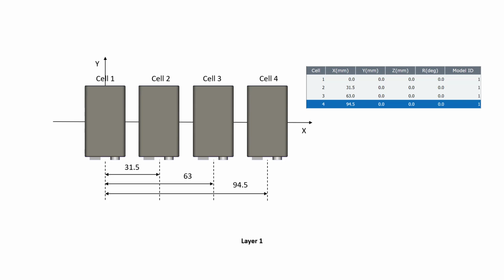iRPickTool assumes that the plane for the X and Y axis for the tray is on the same plane as the tracking frame for the conveyor where the tray is located. In our case, it's going to be the pre-grouping conveyor. And the pre-grouping conveyor has the same tracking frame as the in-feed conveyor, as we're going to see later.